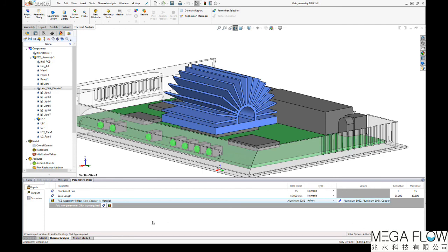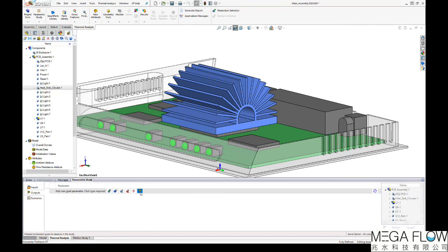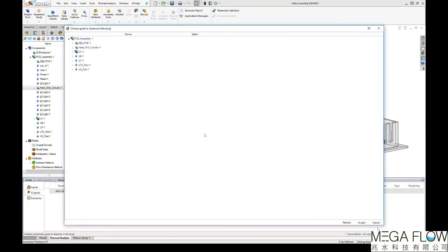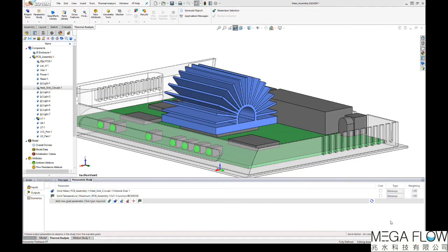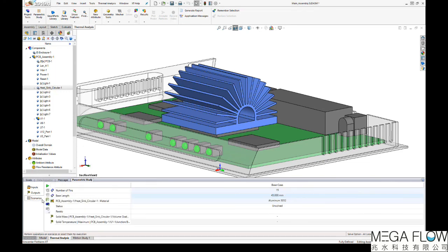Cost functions for the optimization process are usually set in the external tool. It is also often possible to define constraints on the input or to define a study to say minimize my heatsink weight, but ensure that the junction temperature does not rise above 90 degrees C. Once the parameters have been set up, it is then simply a case of creating a task file which can then be imported into the external optimizer tool.